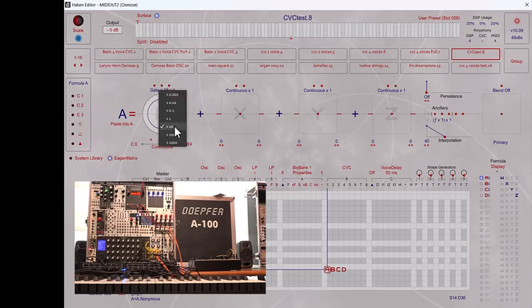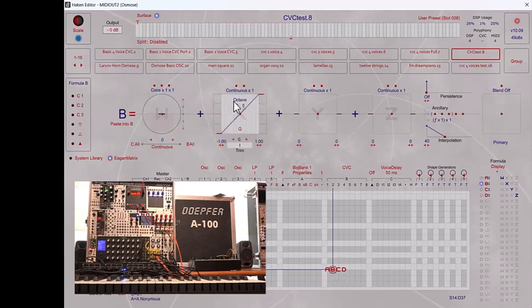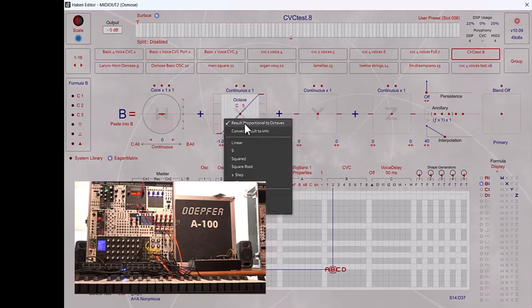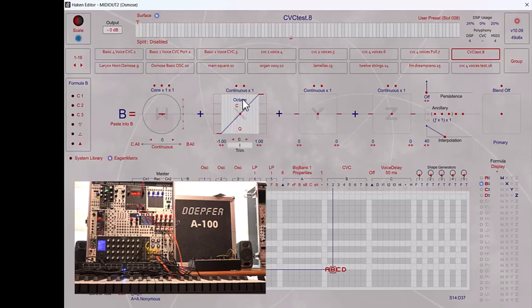I've set my scaling to 10, I've gated W, so now when I gate on W, I'm going to get an instantaneous 10-volt gate. On B, which is pitch, I've set my standard X function min to max, but important here, I have to set octave mode, not kilohertz mode. Clicking in the middle, you can see I have result proportional to octaves or convert result to kilohertz. Well, kilohertz has no meaning in my CV world here. I need to convert this 1 volt per octave, so that's why I'm going to use my octave option here.